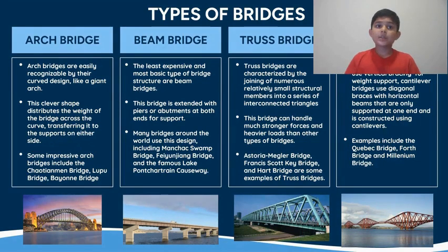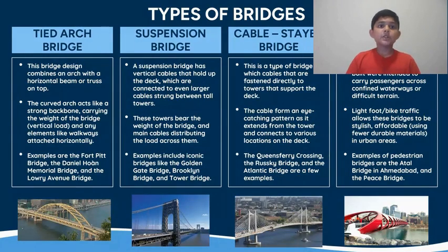Beam bridges are the simplest and most common type, consisting of a flat deck supported by beams at each end. Arch bridges are known for their strength and elegance, using curved arches to distribute weight evenly. Cantilever bridges use rigid beams projected outward from supports. Suspension bridges are ideal for long spans, with their decks suspended from tall towers by cables. The earliest bridges ever were pedestrian bridges.